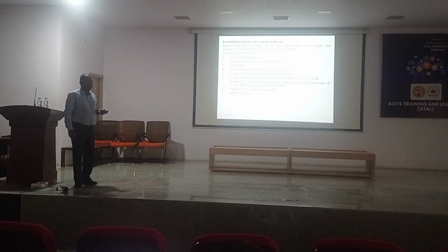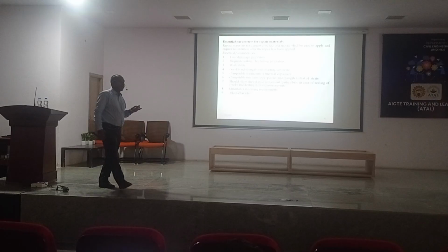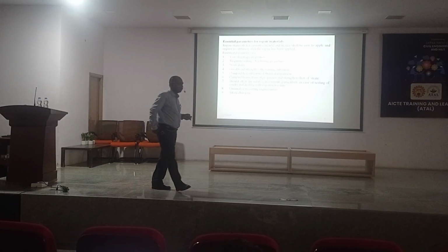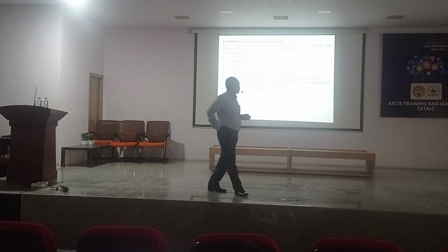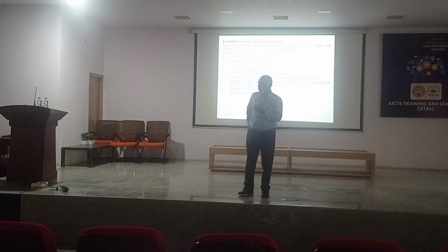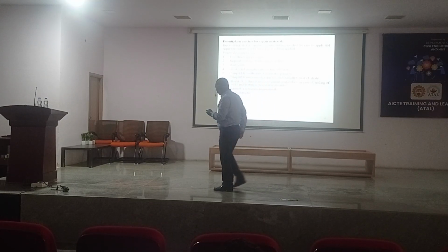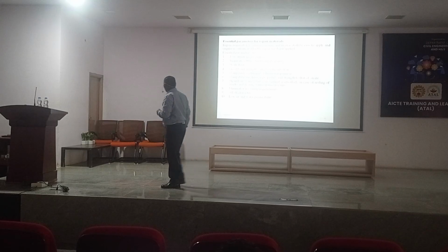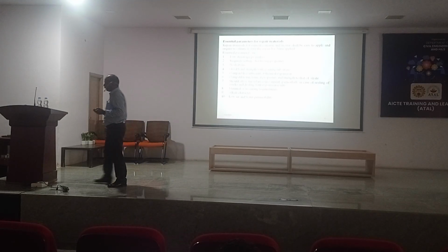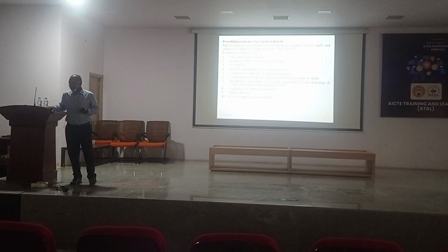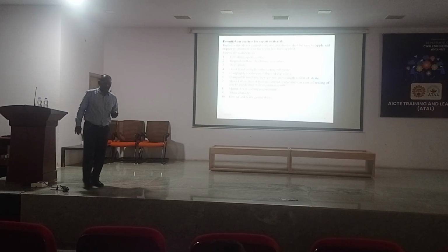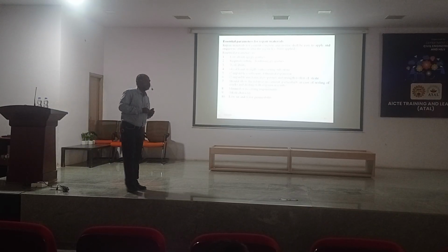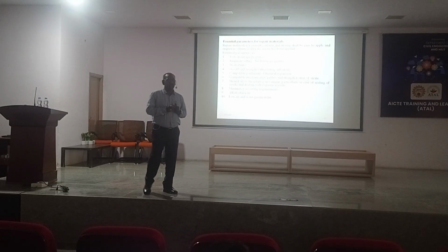Okay, alkali character. The repair material should have alkali character because cement mortar or concrete is alkaline in nature, not acidic. Therefore, this mortar should have alkali character. And low air and water permeability, because the cement mortar or repair mortar should be more dense. All the voids should be filled.